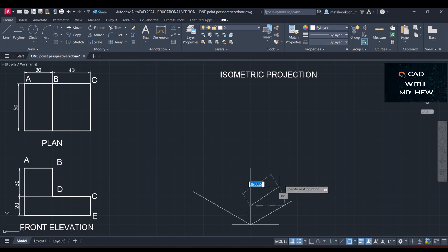All right. So from this point, I can draw the parallel line from C. So it would be 50, and the angle would be 30 again. Right? Good. See that? Then we do the next thing over the next side, right? So come here. What's the length of this side? 40, and the angle is there. Good, right? Then we're going to go B to D, which is 30. So we're going up 30.